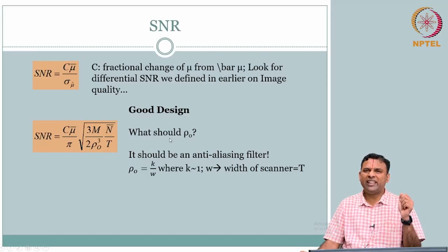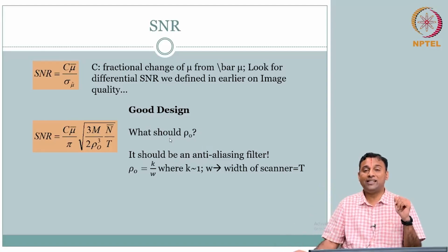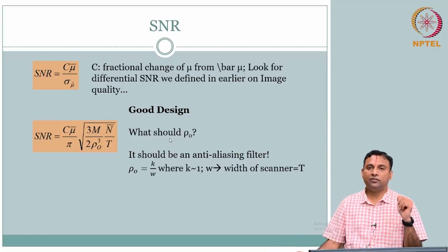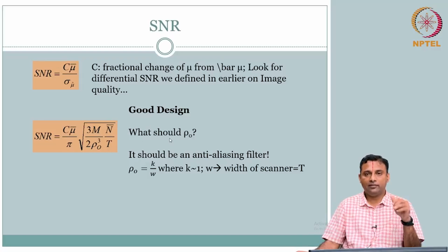When you have discretization, some filtering, the first concept that comes to your mind is the anti-aliasing filter, right. You should have the filter such that the Nyquist criterion is met. You have to have at least twice the highest frequency, otherwise you will have aliasing, which we will talk about also as an artifact, but so here is your control.